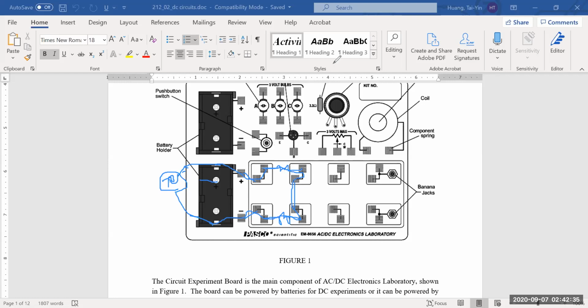Okay. Now to measure voltage. So let's say I want to measure voltage. I have a voltmeter here. To measure voltage, this is my positive. My positive should be connected to positive, and then the com here is connected to the other end. Okay, and then if I want to measure the voltage of this side, which is more positive, my positive will clip on any place within this spring, and my com will connect to this spring.